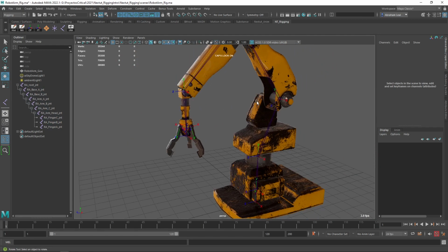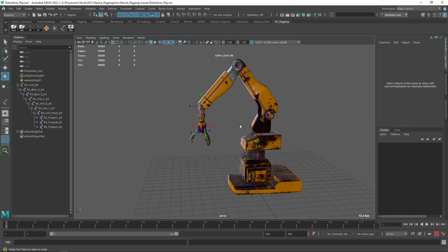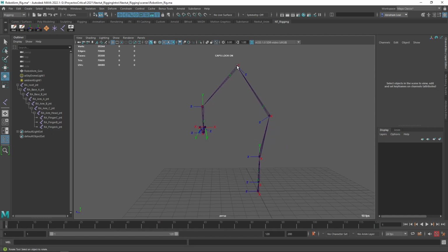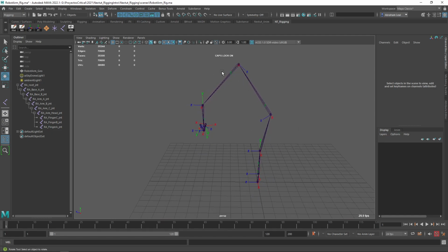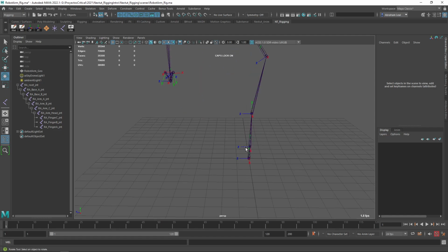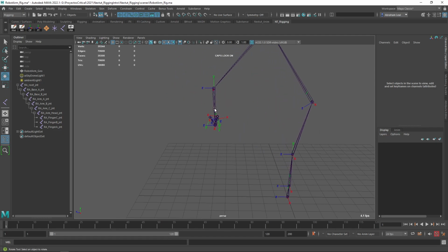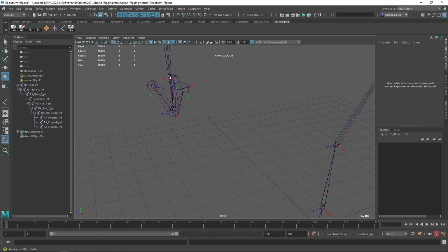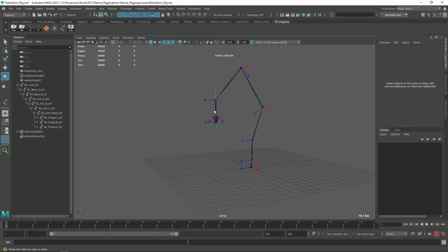And yeah, so that's it for this video, guys. Make sure you get your skeleton looking like this, completely nice. All of the arms, for instance, this first arm and this second arm, they're pointing towards the next one just to keep it clean. These guys are oriented to the world. These 2 guys are also oriented to the world. And of course, the little things here are oriented towards the tip that we just deleted. So that's where it should be. That's the result that you should have.